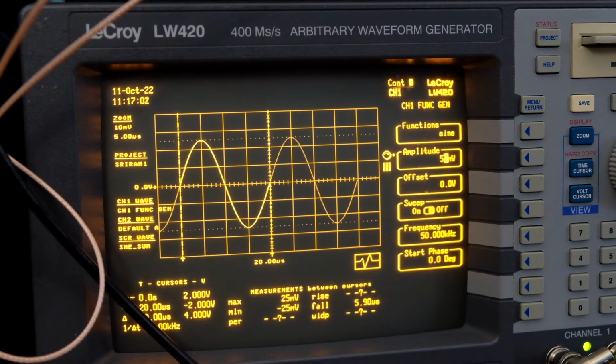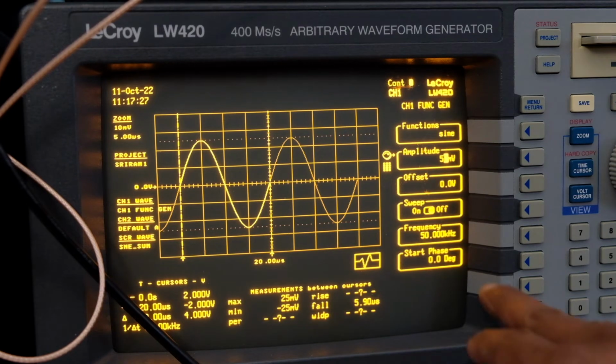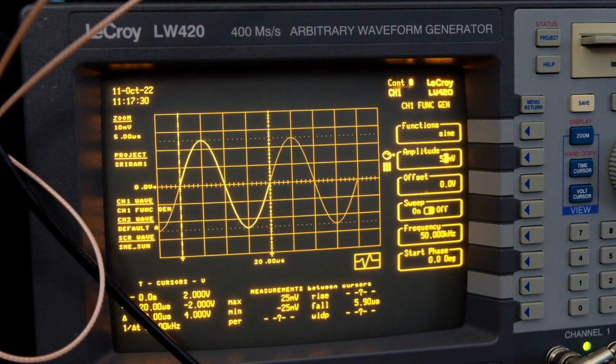So here's a bunch of experiments we're going to try to see the effects of externally induced disturbances on a smooth continuous sine wave signal and see the effects of different frequency components being injected into the signal to see how that affects the magnitude and phase of the lock-in amplifier. So here we have a straight 50 millivolt sine wave input at 0 degrees, 50 kilohertz, and another signal I'm going to try is going to be with some noise injected into it,